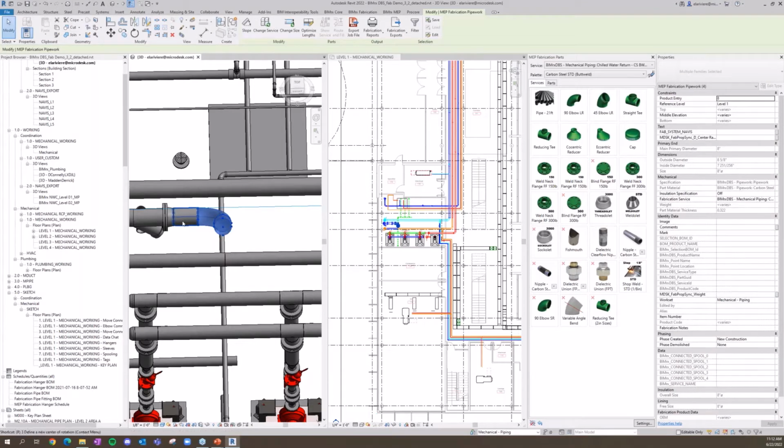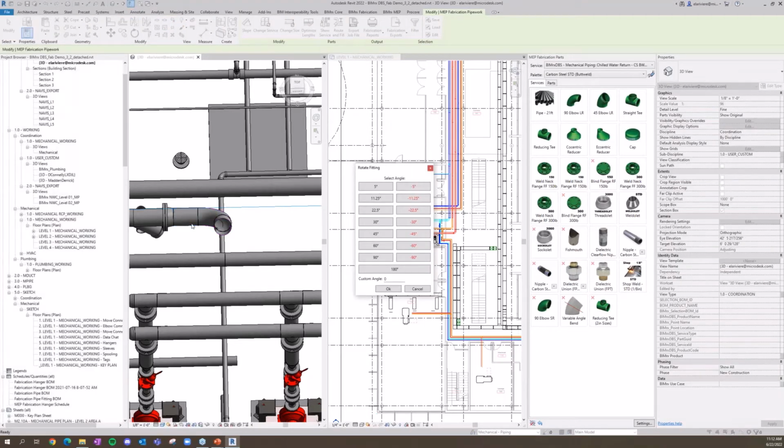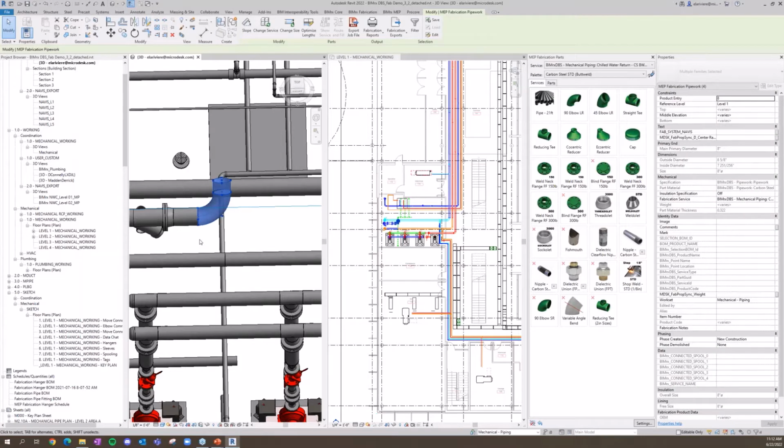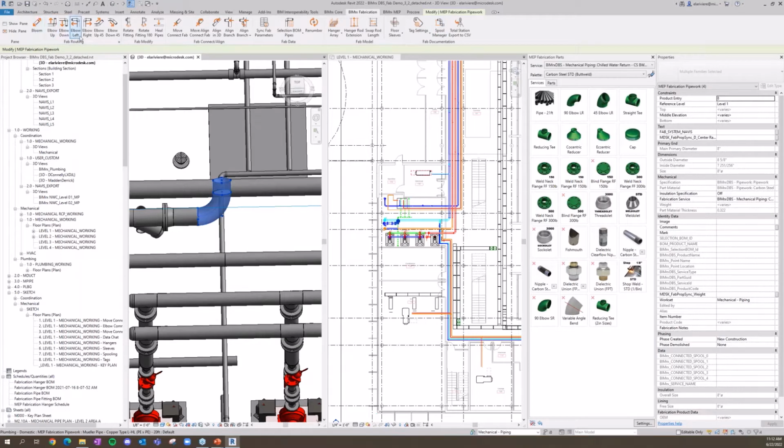But wait, Ed, that went the wrong way. You know, sometimes it's hard to figure out exactly which one is positive or negative. Until you get it right, it's really quick to just hit it with a negative value afterwards. So again, you'll notice I'm not necessarily clicking all these buttons, right? Everything you see me do, every command in BIMrx can be keyboard shortcutted. And we remember your previous selection. So it's very, very quick to just key that command up again and choose something different.